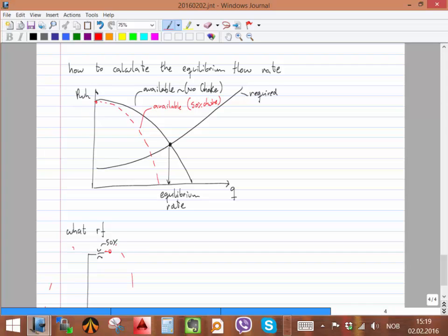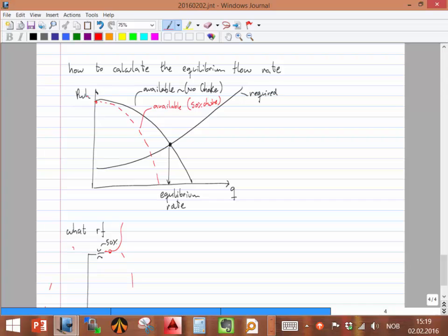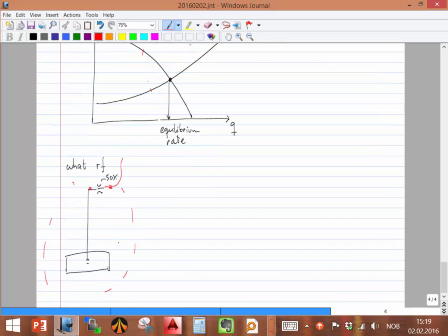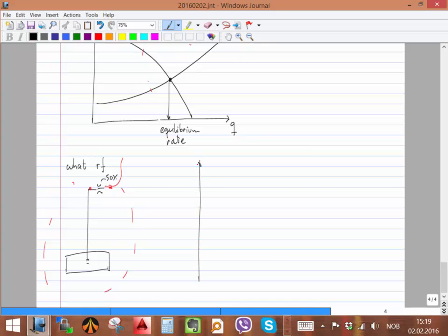Well, it depends how you call it. In this case, I'm saying that the wellhead is here. It really should be the pressure downstream of the choke, if you want to be formal. What Bilal is saying is that you cannot call it wellhead, since that is the pressure upstream of the choke. We should call it differently, right? So we say one curve, and we call it pressure downstream of the choke, DC.